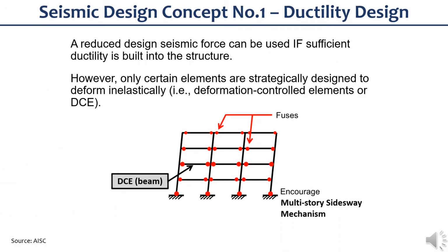Let's relate the fuse concept to seismic design. The first seismic design concept is what we call the ductility design. A reduced design seismic force can only be used if sufficient ductility is built into the structure. However, only certain elements are strategically designed to deform inelastically. That is, the deformation controlled elements, or DCE. Note that in SMF, the DCEs are the beams.